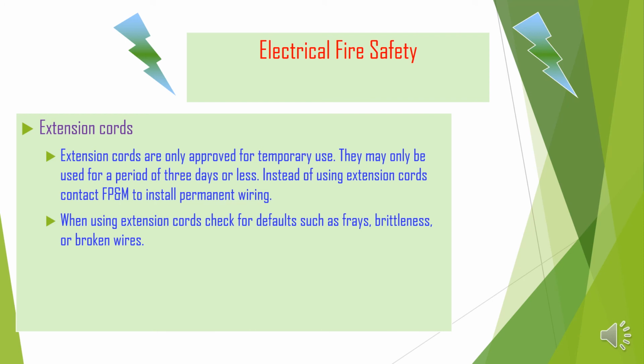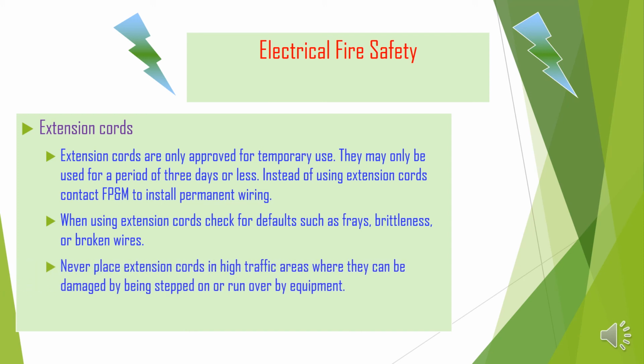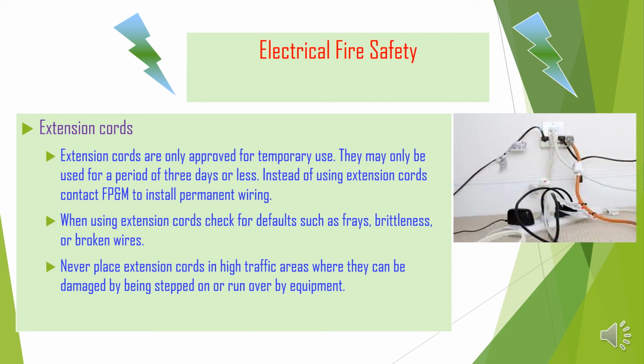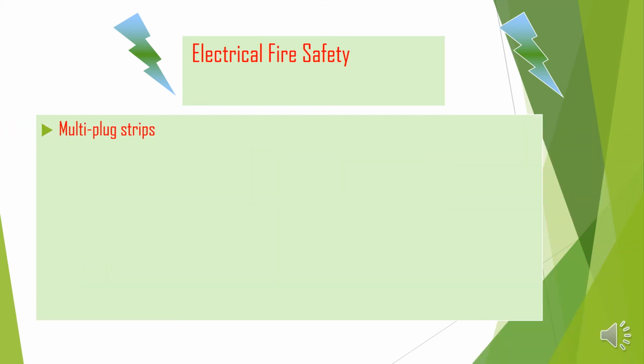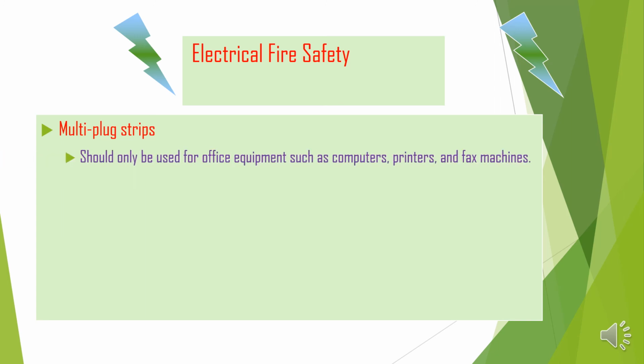When using extension cords, check for defects such as fraying, brightness, or broken wires. Never place extension cords in a high traffic area where they can be damaged by being stepped on. Extension cords with a lot of outlets are a very, very dangerous situation. What about multi-plug strips? It's another cause of fire inside our healthcare facility.